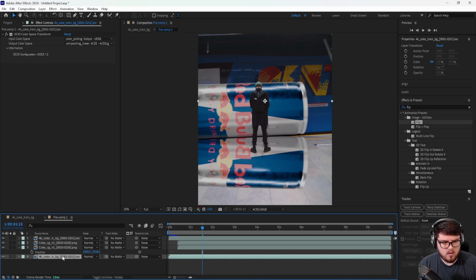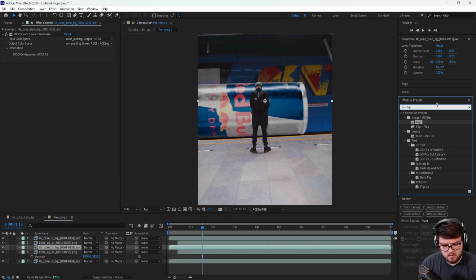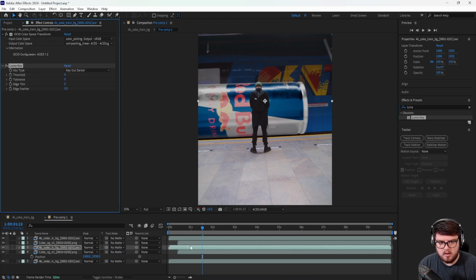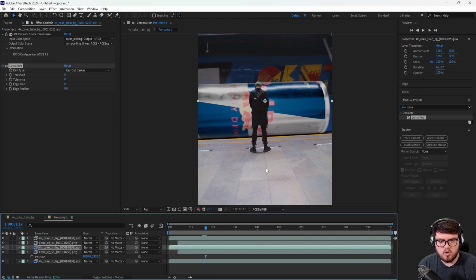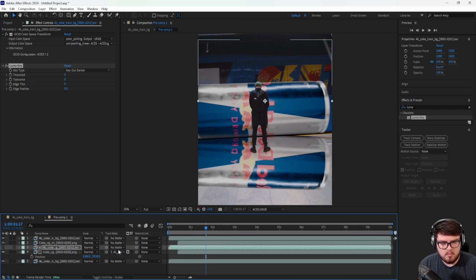So I'm going to duplicate our original footage pass. We'll put that over top of it. And then I want to go ahead and do a new effect. We'll come over here. I'm just going to type in Luma key. We need a Luma key right there. Place that on here. And what we're trying to do here is introduce some kind of breaking up of the reflection. And so in order to see that, we'll go ahead and do our luminance matte right there and set our track matte there. If you can't see that, you just have to toggle switches and modes, by the way. So now we have that.